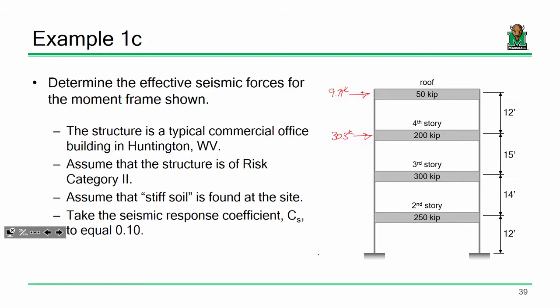Does directionality matter? Direction. No, because that's a good question. And no, because it can go either way. But that assumes that your building is symmetrical. Well, there are other issues as well. It's similar to what was going on with wind. Under an earthquake, the building might not just want to go this way; it might want to rotate, just because of its plan profile.